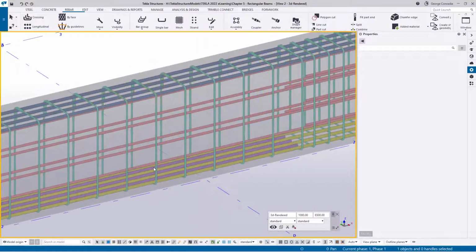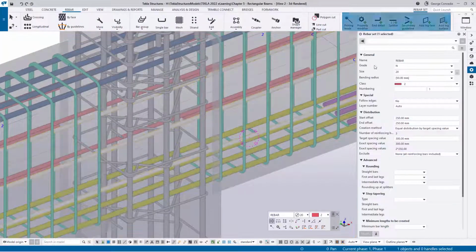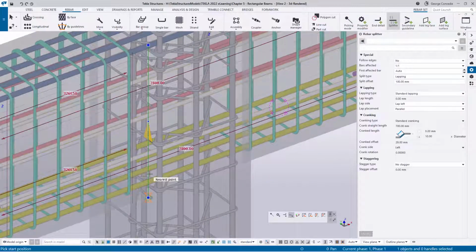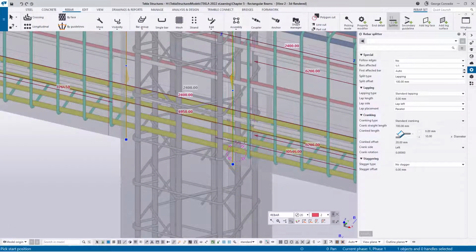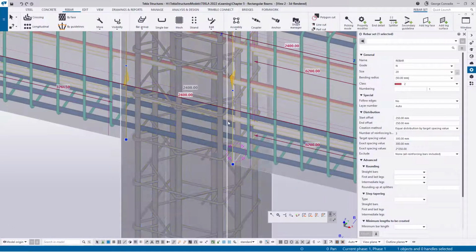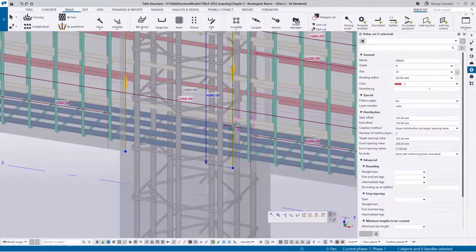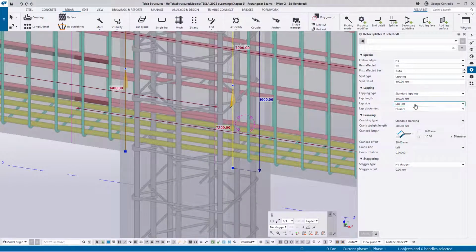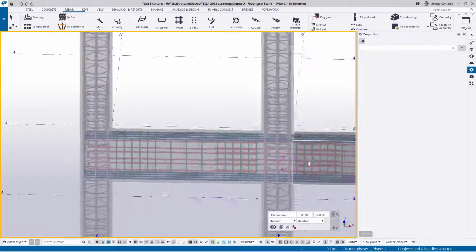So if I click on the splitter, I can just flick it over to the left, modify, and that fixes up that connection. And then obviously lastly, and these can be copied, but I'm just doing it manually for the sake of the drill, and also because I'm seeing too many bars at the moment. Again, you can see that the lap's on the right, the lap's right, but the direction is wrong. I like to keep my directions the same, so I can move it back to the right, then modify. Just like that, we've got the red bar sorted.